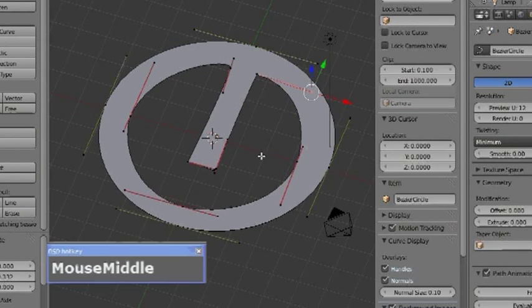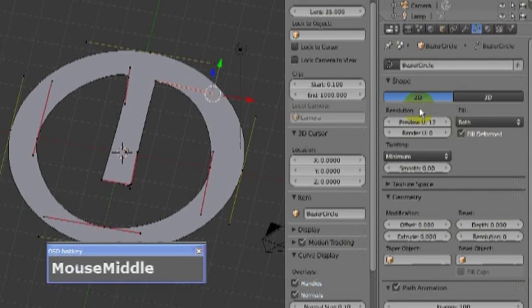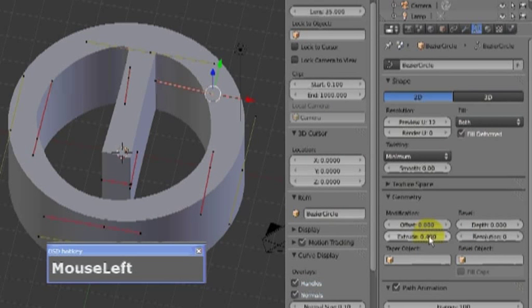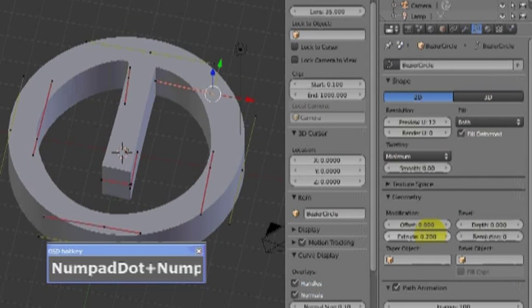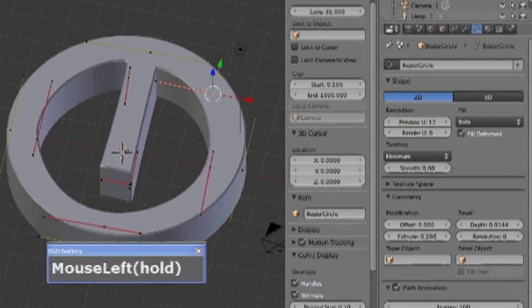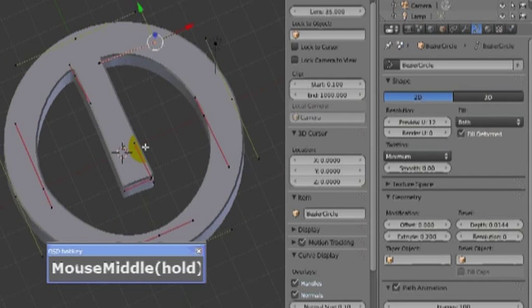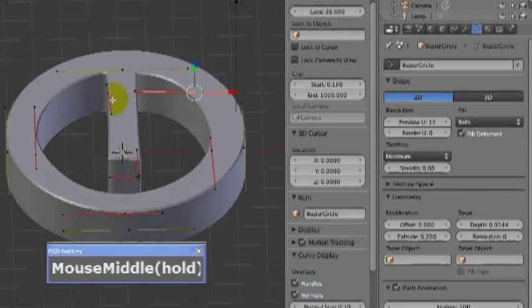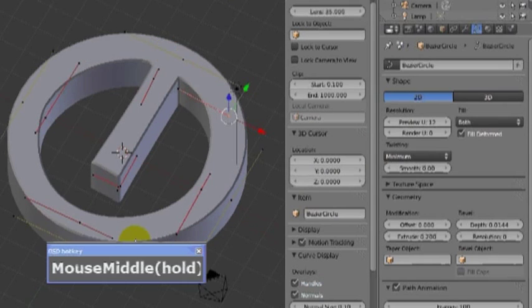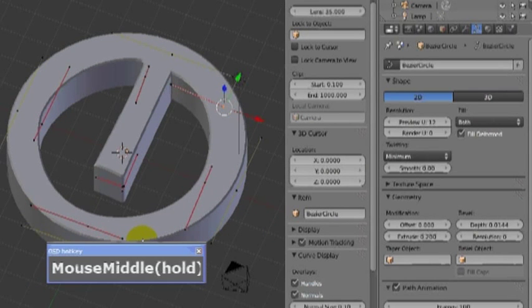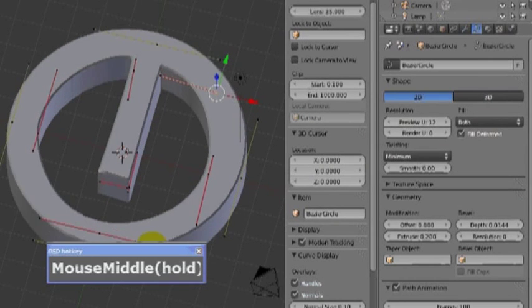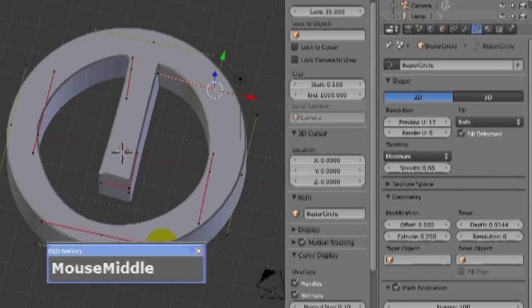Now what we're hoping to do is to turn this into a 3D object. To do this, on our far right hand panel in the object data for the curve, we can find extrude and we can extrude that up. Often it's better to add in the numbers. We can also bevel, and we have a 3D object. You can then convert that curve into a mesh if you need to, but at this stage a curve will give us a nice clean look.